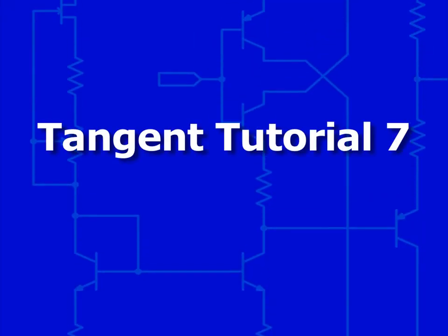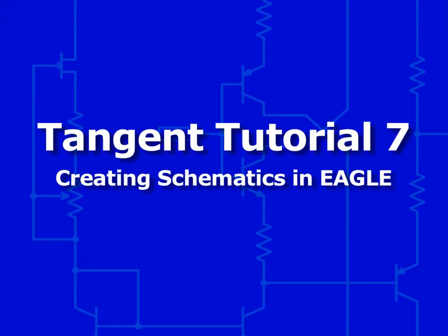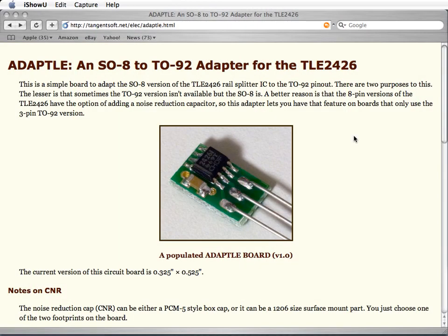This is Tangent Tutorial 7, Creating Schematics in Eagle. In this tutorial, I'm going to introduce you to Eagle, starting with a schematic for this Adapt TLE circuit. All it does is take this TLE2426 part and convert it from this surface mount pinout to the 3-pin layout that you see right here, and it will add a capacitor to one of its pins. So it's a simple conversion board, and it'll provide a real gentle introduction.